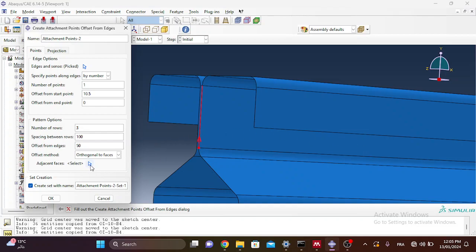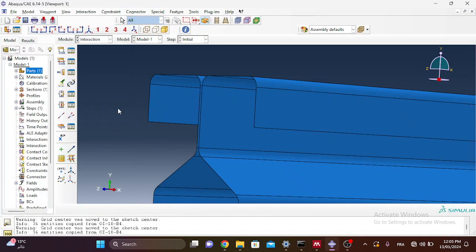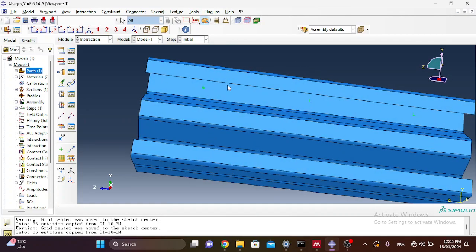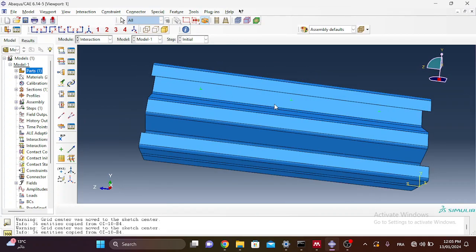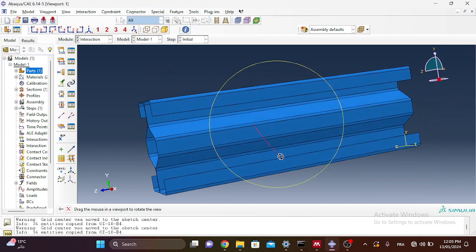the screws will be located. I click here and I click there. Okay. So as you can see, the upper line of screws in the web are already modeled. This is only attachment points that we will take to introduce my mechanical properties of screws after I finish modeling the down part of screws. In the down part, we will do the same operation for the attachment points.